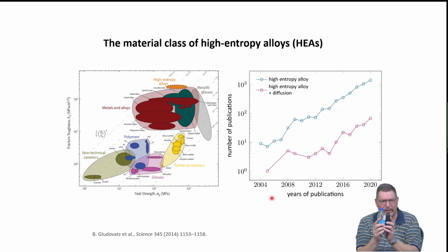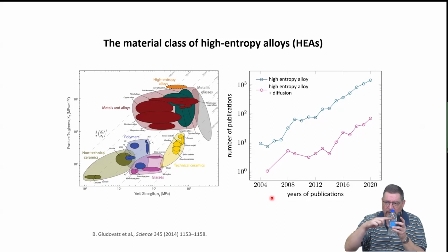many people put material A and material B together. Then they give it some time at some temperature. Temperature translates to kBT, right? You give it an energy for the atoms to become mobile. There is some Brownian motion, and there is a concentration gradient, because this is a different material than this. So interdiffusion will happen. Some atoms of this part will diffuse in this direction, and some atoms of this will diffuse in the opposite direction.